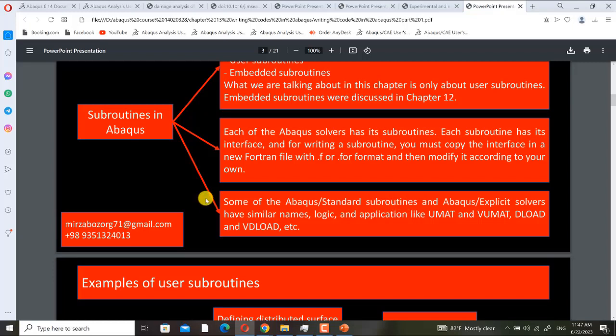Some of the Abaqus Standard and Abaqus Explicit subroutines have similar names, logic, and application, like UMAT and VUMAT, DLOAD and VDLOAD. You can see that only the V is different between their names, and both of them have similar usage, and even similar interfaces.